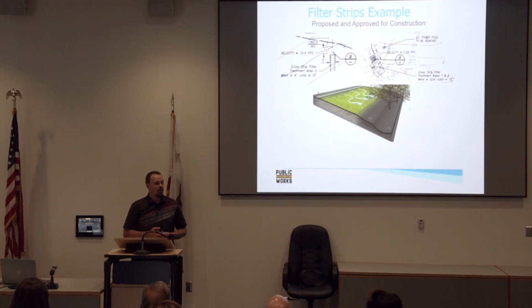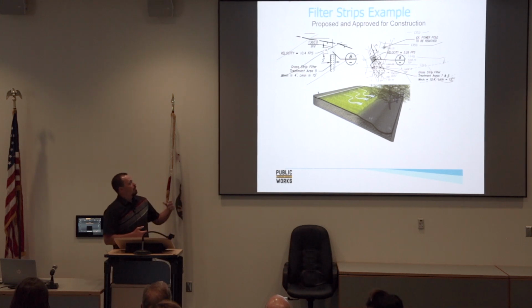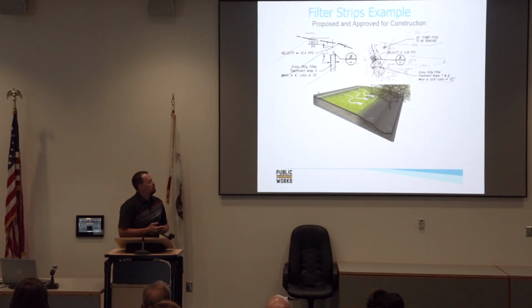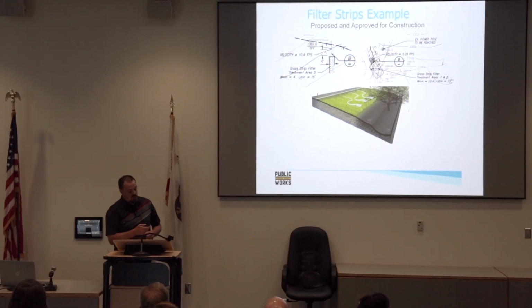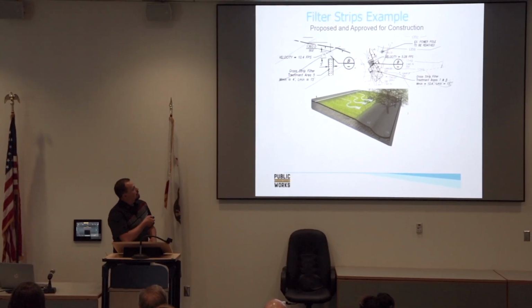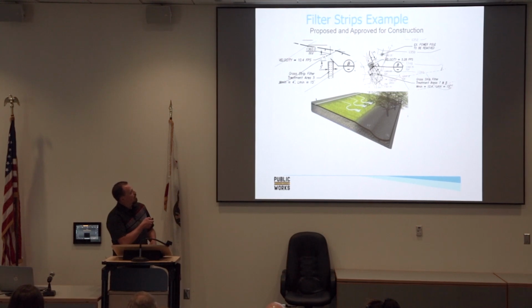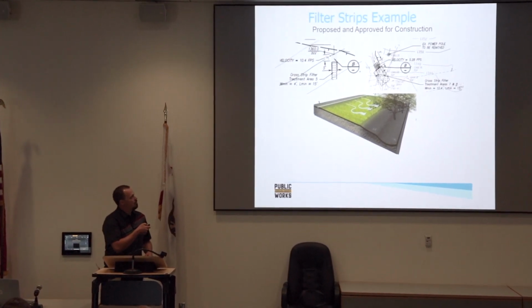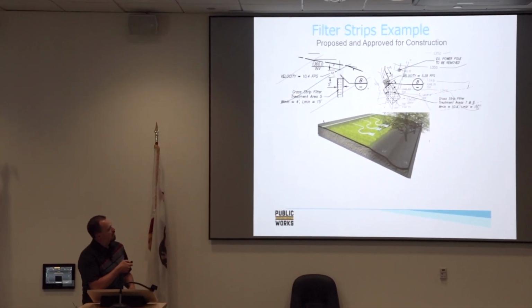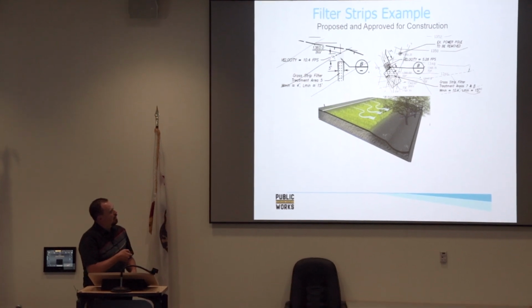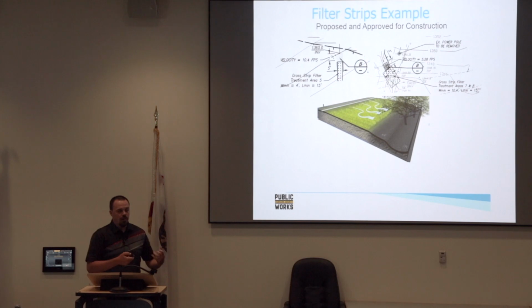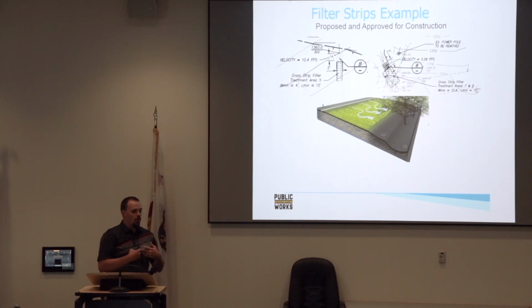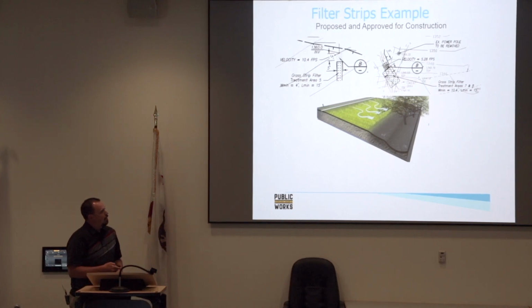design and construction. On this side, we have a project that was designed with filter strips as their biofiltration requirements. So at the end of their discharge points, they have energy dissipators, and then those would disperse across these filter strips, and they had 2 of them at their 2 discharge points. And then here's just a general picture of what filter strips generally are. Very flat, have to be about 15 feet in length so water can flow through it and filter.